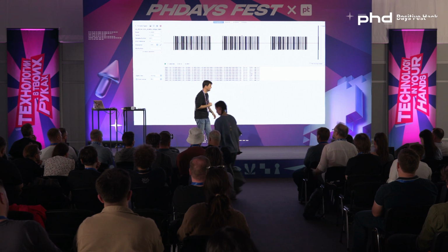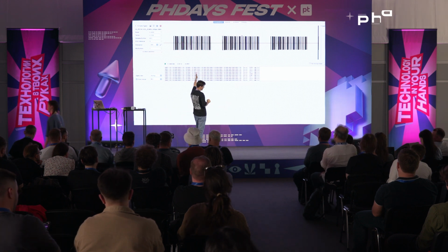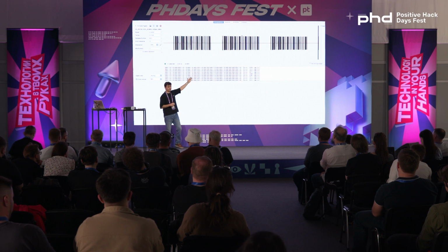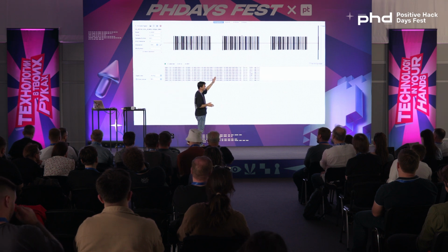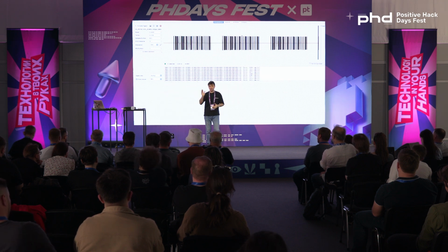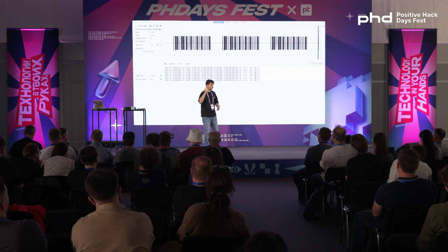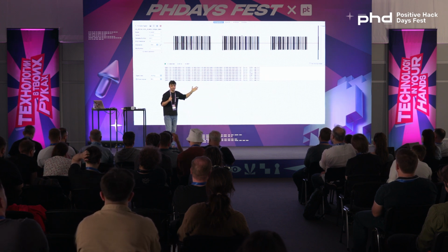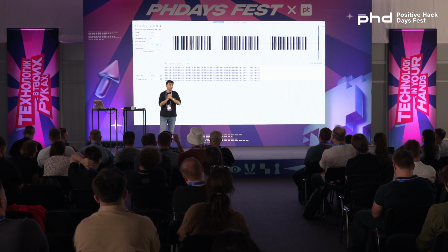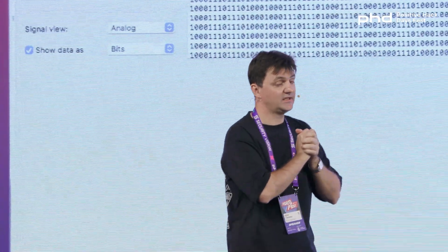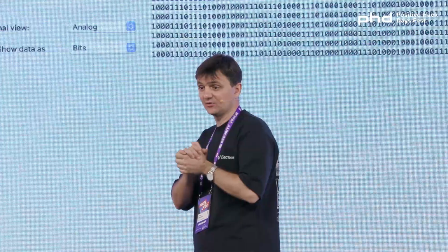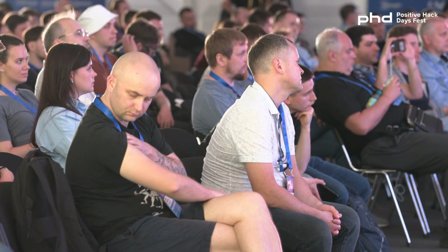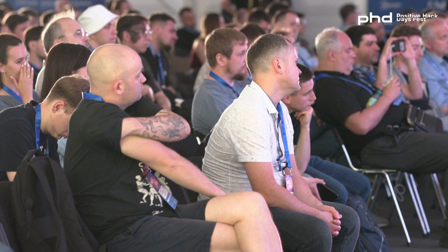That was a correct answer. I'll restate it with the mic. The signal is repeated however many times. The code is the same. You press the button, it sends the same payload. This is what makes replay attacks possible. You record it, you replay it.